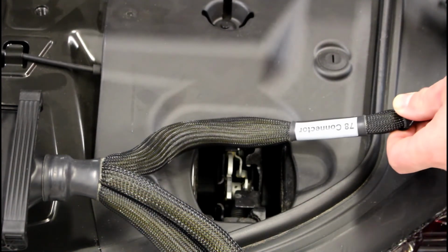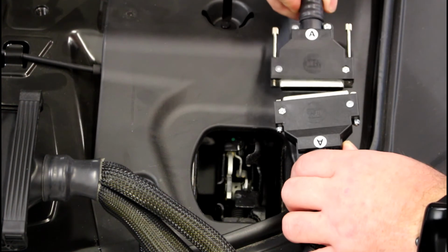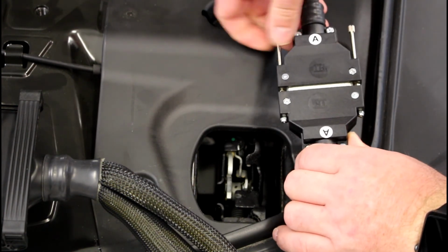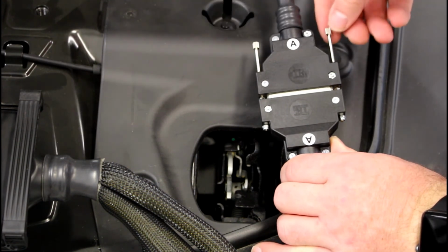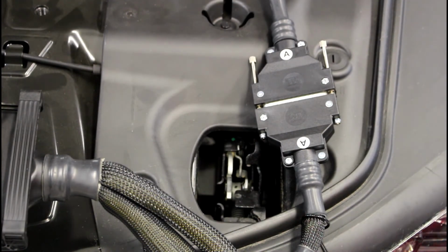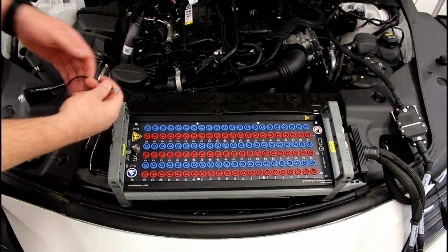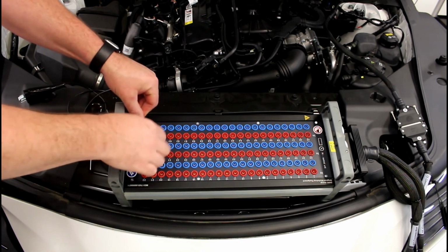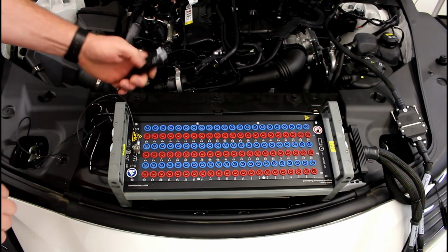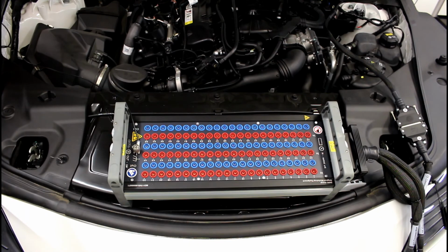Okay, so let's connect our breakout box to our piggyback harness that's connected to the DME. Once it's nice and secure, I'm going to go ahead and put in the set screws and we're ready. Last thing to do is to go ahead and connect the supplied ground for the breakout box. Screw that down on the set screw, and then I'm just going to take ground right to that post where we have the DCA 8000 connected.